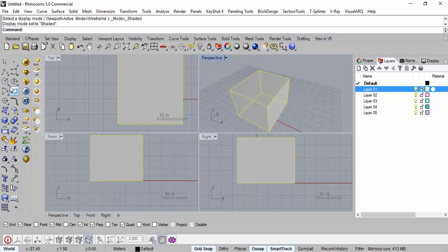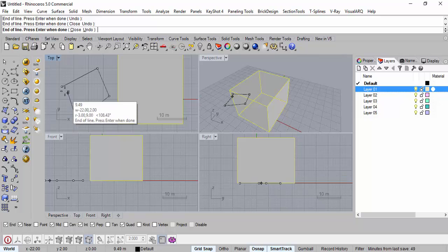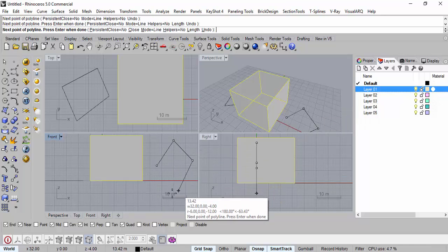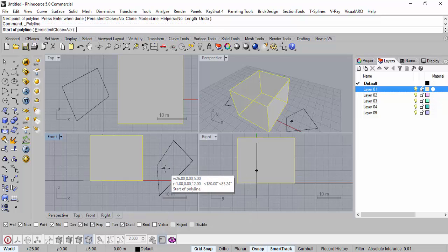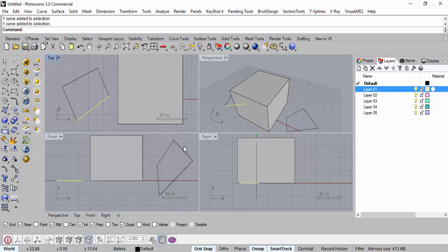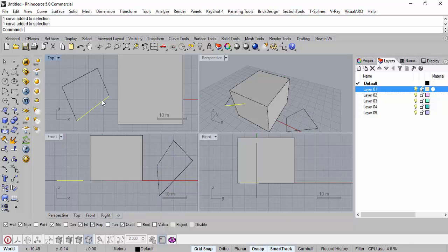So when there are two tools shown, for example, here again you'll have to see polygon, line segment. If I want to draw a line segment, I right click on this, click 1 and 2. So these are line segments. If I want to use polyline, I click on the left and then I can draw. See, as I'm drawing, it is reflecting in other viewports. Are you getting it? Fine. So what is the difference between the line and the polyline? Polyline becomes one single object, whereas with line it allows you to draw continuously, but then it gets split. This is clear?